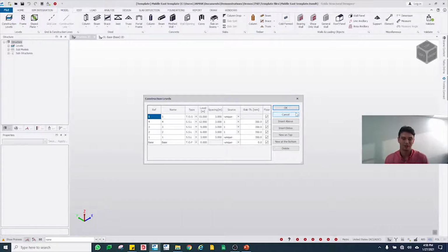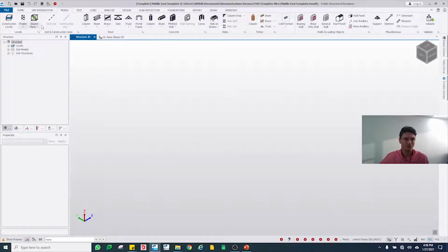Just to let you know as well, crucially, we give the level a type at this point. That allows us to create the drawings accurately in terms of where the physical members lay out, as well as integrate well with BIM software such as Tekla Structures and Revit. Grid lines I'll come on to, but we can model steel work: columns, column filled, encased and plated, different steel beam types, bracing, portal frames. If you're doing industrial sheds as an example, we can model portal frames very intuitively.